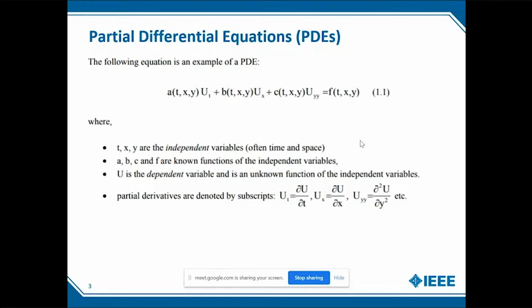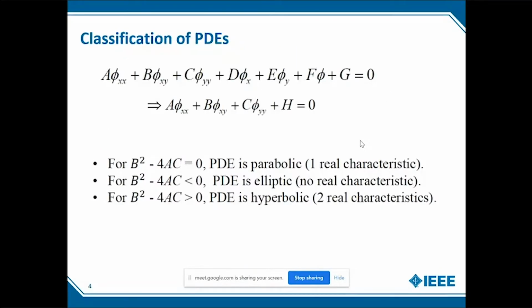These are pretty important if you're doing a basic CFD simulation. Coming to how we use partial differential equations in CFD, to explain the different partial differential equations, just consider the equation that you see on the screen. Whatever I'm talking about right now is just applicable for a second order partial differential equation and not for higher order ones. We group the first derivatives and all the other constants in the term h. We are mainly concerned with three terms here: double derivative with respect to x, double derivative with respect to y, and a mixed derivative term.